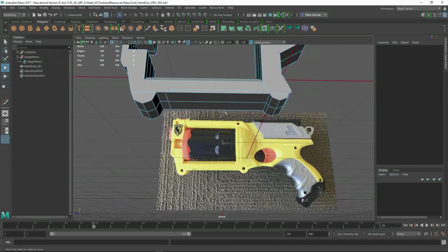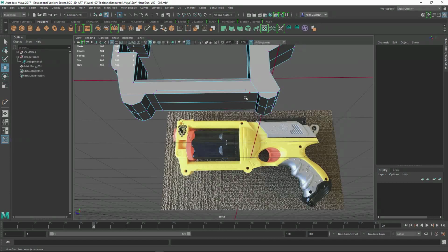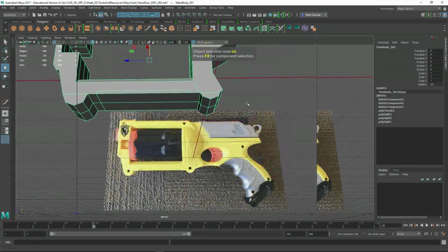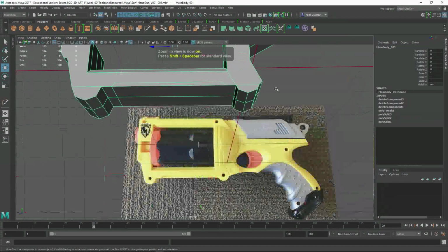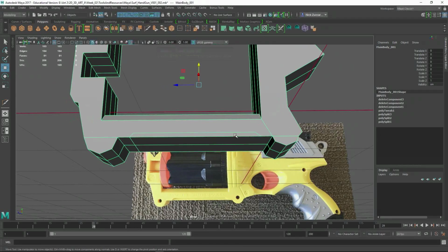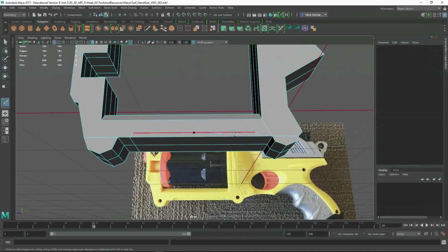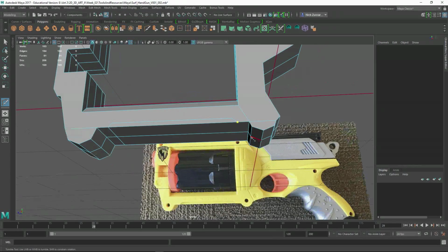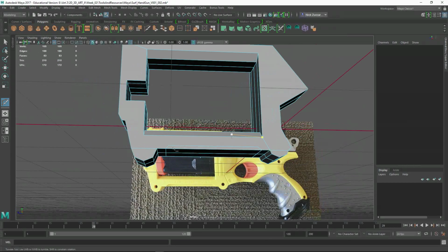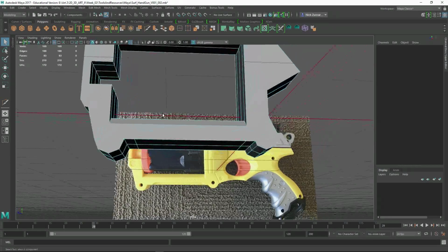So now we've got something like this. I need a split going all the way down here, so I'll go back to the multi-cut tool. Sorry, I'm just going to zoom in on here. Shift right click, multi-cut tool, go across here, hold down Control and Shift, and there you're going to see it gives you that 90-degree angle, which is nice. And so cutting across there, this is kind of like a notch that's extruded in.